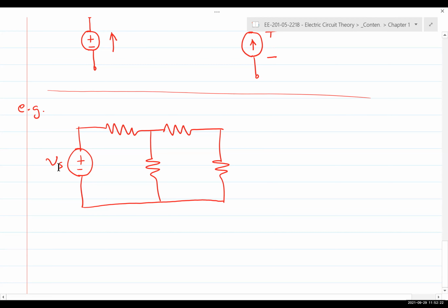But those assumptions are based on logic, right? The logic here is that if Vs is given as plus up top and minus at the bottom, which direction do you choose for the current? Up, right? So it's going up, from minus to plus. So current goes from minus to plus. Make sense to everyone, right? Now, you're driving around, you start driving from this point, there's only one pathway to take. Going up there, make a right turn, so to speak, so it's going to go through the resistor this way.